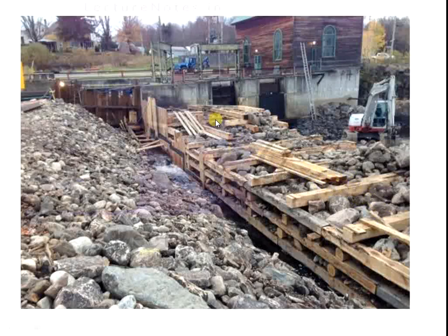These pockets are filled with either earth or stone, which gives better stability against overturning. This type of cofferdam is used where the water depth is up to 10 to 20 meters and the velocity of the flow is fast.